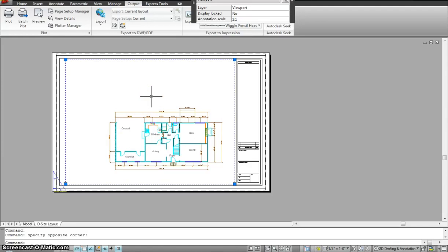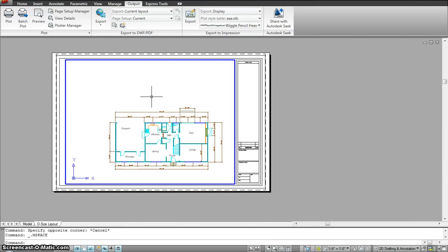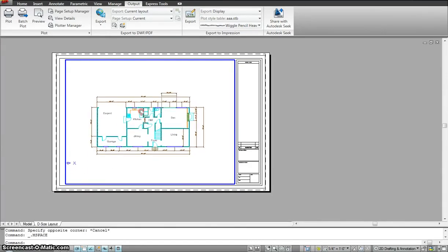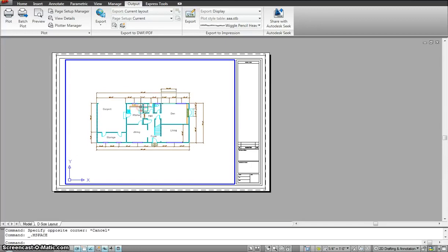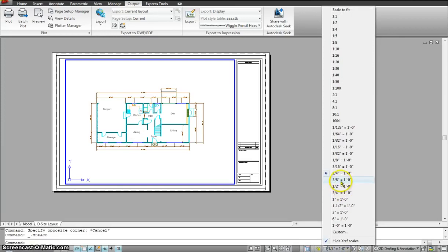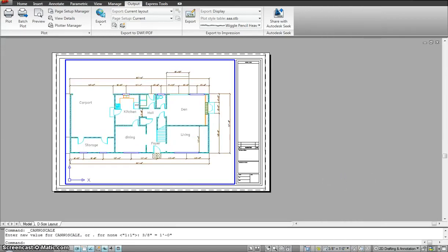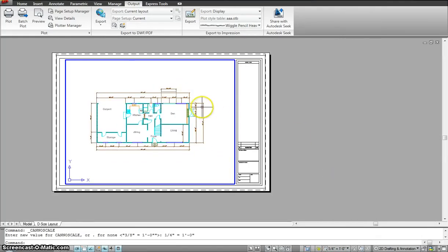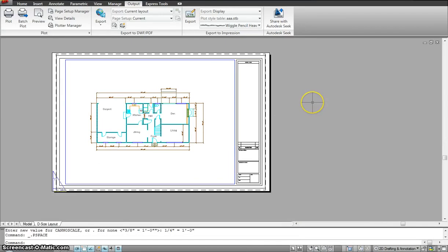So now once my viewport is unlocked, which I did right now, I'm gonna go double click inside, and using my cursor, like the scroll mouse, I hold it down and I can align my sheet to where I want. Once my alignment is done, I could even change the scale if I wanted, make it a little bigger, right? But I am going to keep just a quarter scale right now. That's good enough for this exercise.